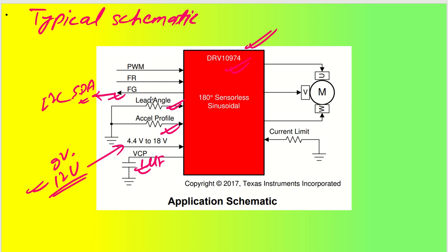That will also do. Next, a very important thing is the FR pin, which is a direction setting pin. You have a motor which has U, V and W phases. So whether you want it in U, V, W or U, W, V, okay. Which way you want to rotate it, either in the forward direction or the reverse direction. This can be set by one of the pins, by a pull up or pull down, or maybe it can be controlled through a microcontroller GPIO as well.